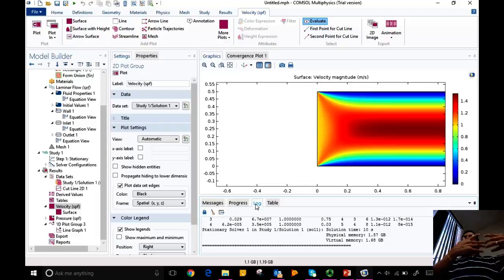And then in those regions where the gradients are high, it puts more grid points, only in those regions. So it's called adaptive meshing. And you specify a global tolerance, and until it meets that tolerance, it will continue to refine that. Okay, that's done automatically once you enable that. Is there a manual way to control it? I think there is. That's a good question. I don't know. I haven't used it.